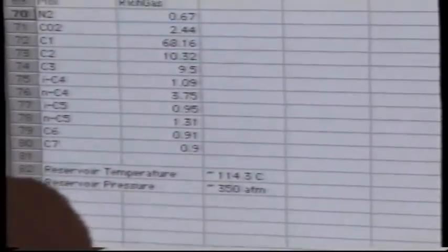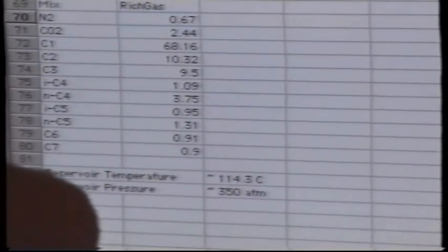The mix is the primary keyword, and now we've named these fluids. Oh, one more thing. You have to take out the space between lean and gas, and also the space between rich and gas. All right? So we're defining 3 fluids: oil, lean gas, and rich gas by name. And we're giving the compositions in this form here.